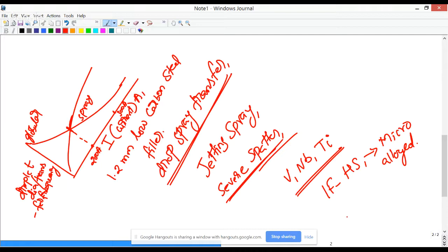Okay, so one question has come from the live stream from Mr. Bhargav. Which parameter is most important to control spatter? It is a very good question. The process stability is determined by various factors, for example, the arc characteristics, and also the weld preparation, the surface preparation. You also have the stability of the power source.